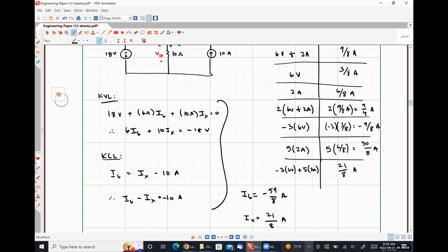Technically speaking, using the principle of linearity, you could break your circuit down into however many different circuits you need with each independent source on once, and you could treat every source as a 1 volt source or a 1 amp current source, and you'd still be able to get the correct answer every single time, okay? That's because of the way that a linear circuit behaves.